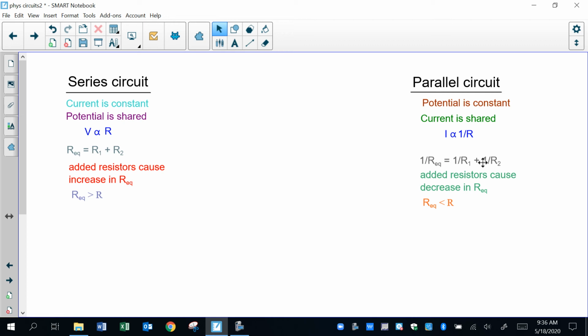And we could do a real quick and easy example of why this is so if we were able to do this in person on a big whiteboard. But basically what this means is that every time you add a resistor, you are decreasing the total. Think about it. Whatever I add up over here, big or small, doesn't matter. Every time I add a number, this right side gets bigger and bigger and bigger. But the right side is equal to the inverse of our total. So as this number gets bigger, the inverse gets smaller.